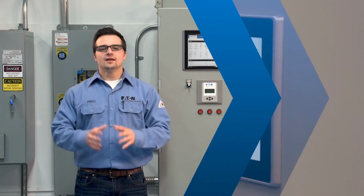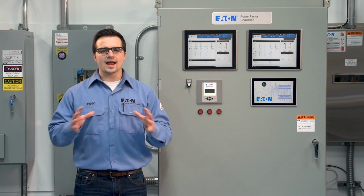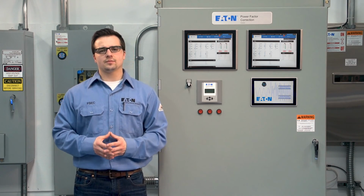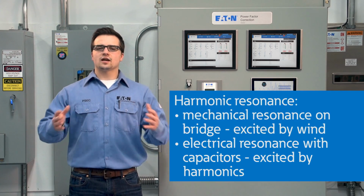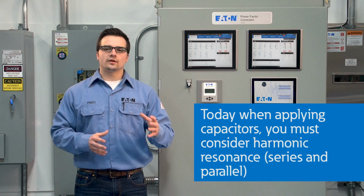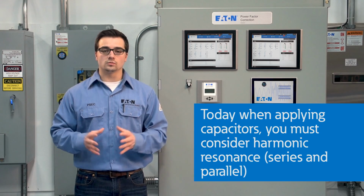Before harmonic loads were prevalent on power systems, you could place a capacitor anywhere on a system without worry. Even though a resonant point was created with that capacitor, there was no harmonic current to amplify, just like if the wind didn't blow to make the bridge oscillate. If there is nothing to excite resonance, you don't have to be concerned. Today, with the amount of harmonic current on our power systems, we have to consider harmonic resonance if we are applying power factor correction capacitors or harmonic filters.